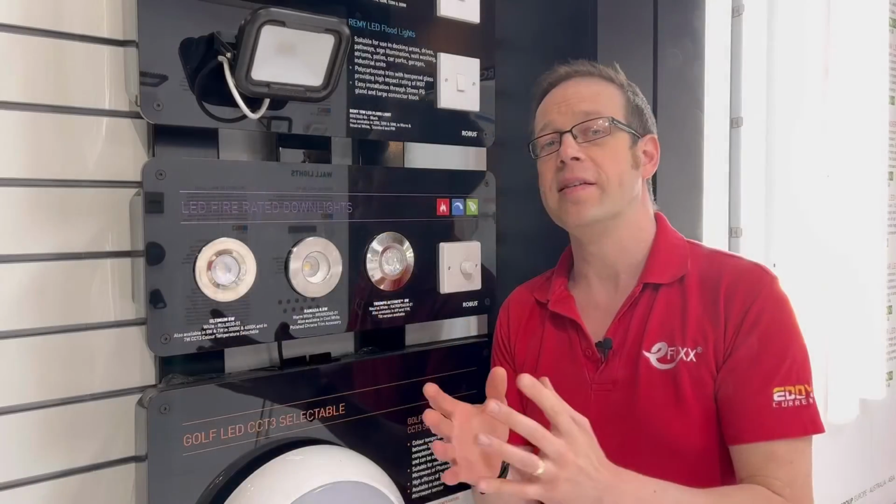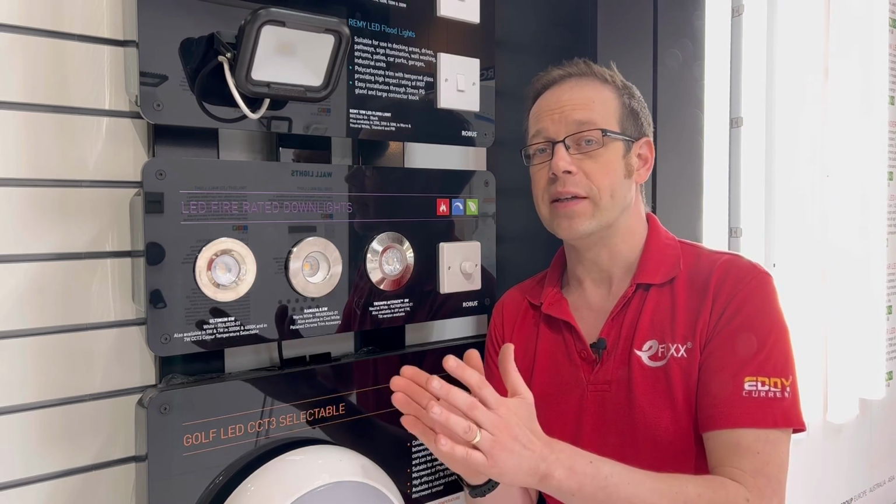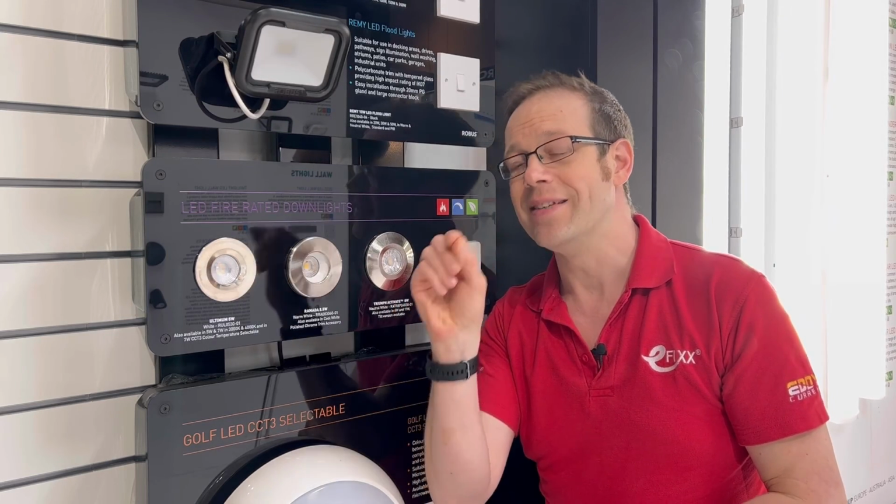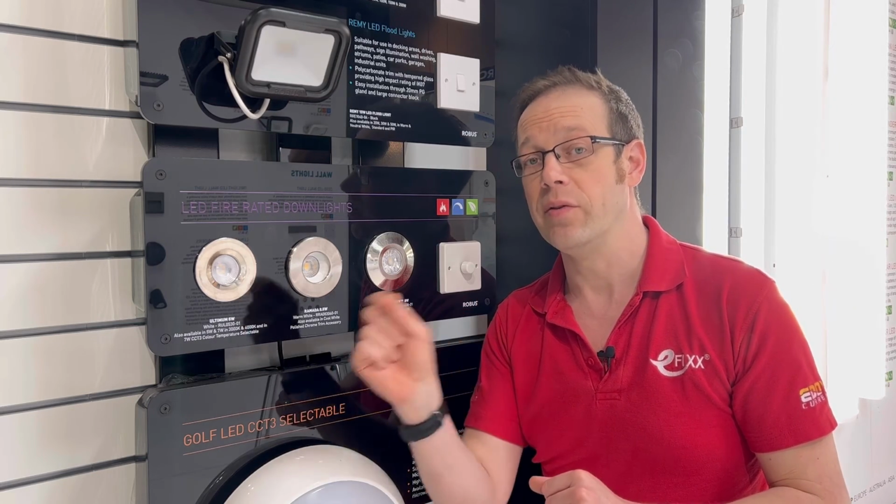This is an important distinction because an LED installed in a light fitting uses a certain amount of power, but there's also circuitry within the fitting feeding the LED, and this also uses some power. So the lumens per circuit watt tells you the efficacy of the total fitting, not just the light source inside the fitting. And most regulatory requirements like the building regs express their requirements in lumens per circuit watt.